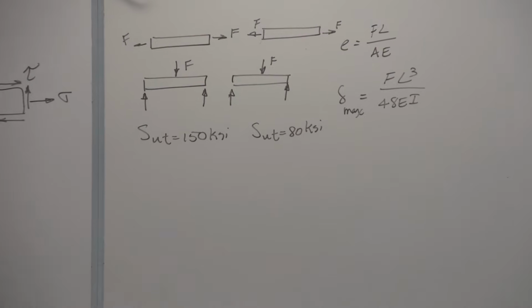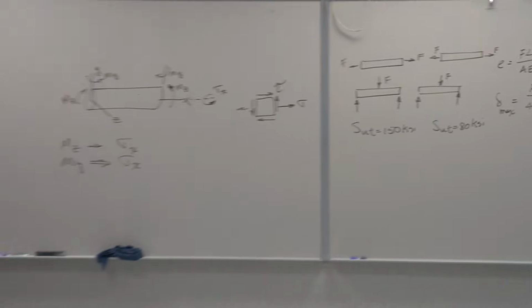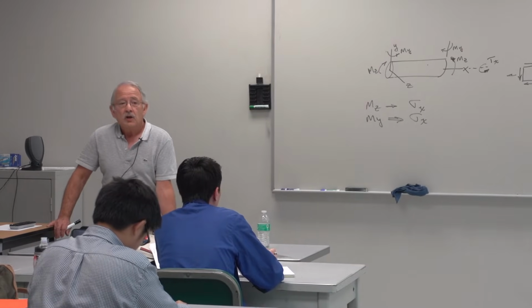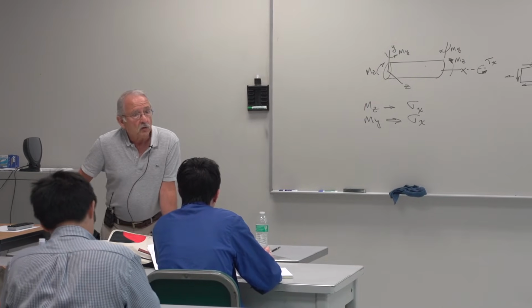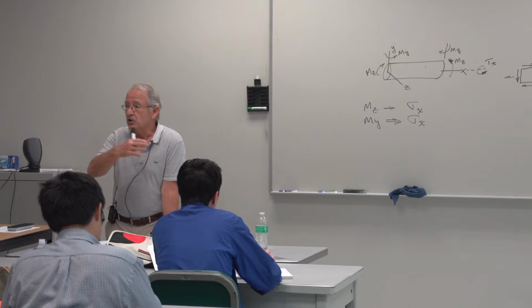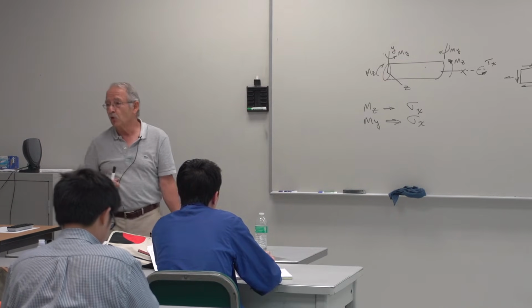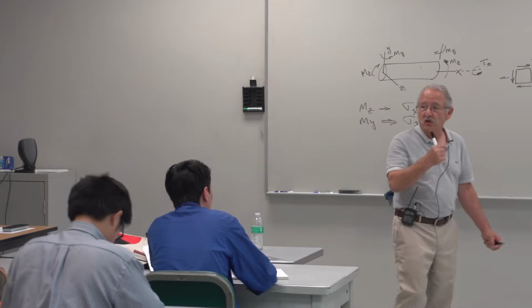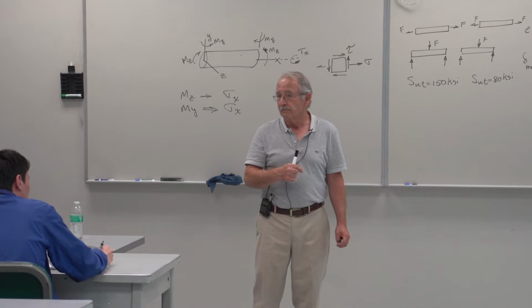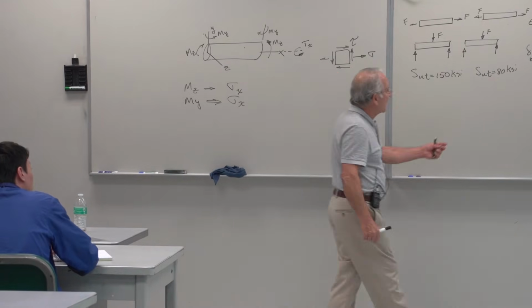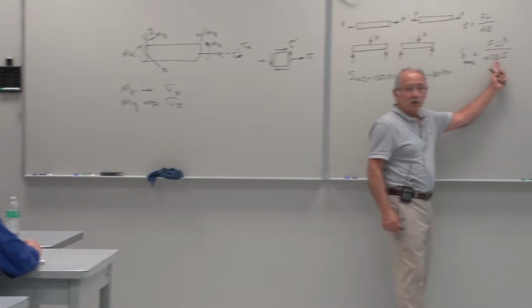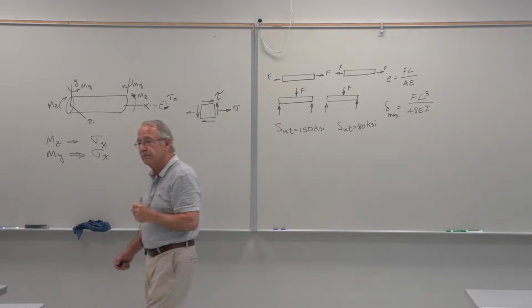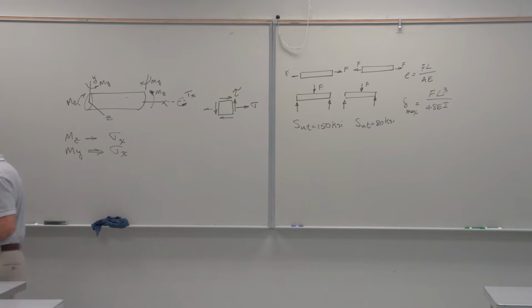The deformation of the shaft, or any other body for that matter, from a materials point of view, only a materials point of view, if I change the length, of course, it's a different ballgame, or the diameter, is solely a function of the stiffness of the material. And that's the only material constant you have here. And that's the same for steels, regardless of their strengths. Therefore, the answer to both of those is the same.